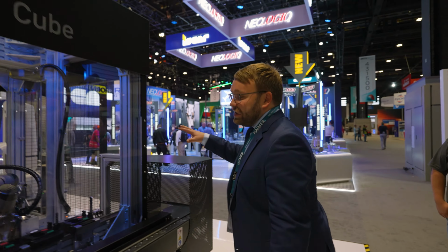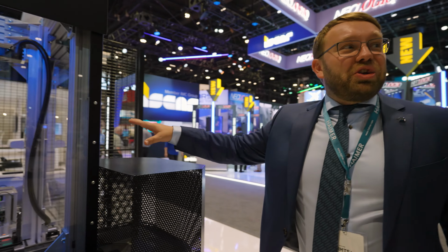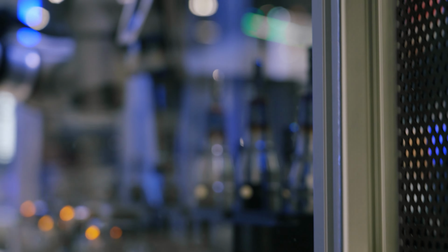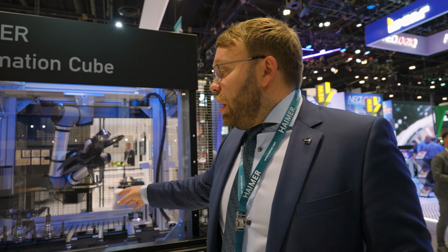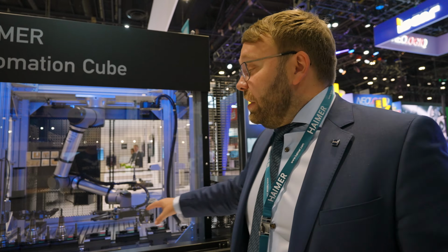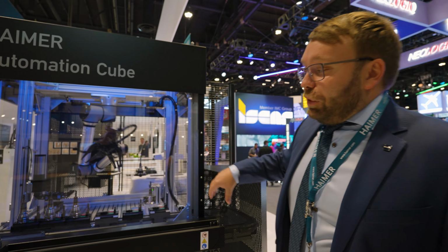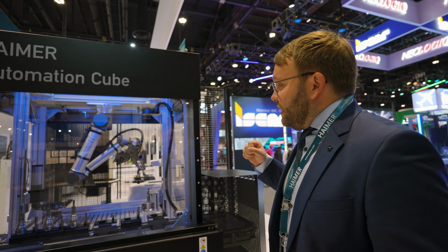What else you got? We spoke about a $14,000 entry-level presetter. This is something else. That's an automation cube, which is a fully automatic shrinking and presetting cell. The idea is for larger shops that maybe want to run a second shift in the tool room, so they can invest in such a cell. It's programmed with our tool management. The robot will actually measure the length of the cutting tool and heat up the holder. When the holder is shrunken in, it will then move it to the presetting process, which we have just seen before.